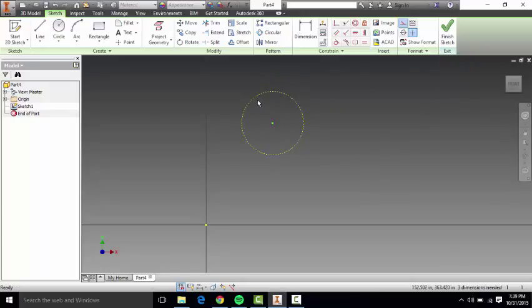And we can see that it is yellow and dotted, unlike if we deselect this and click on the circle tool again. A regular circle is green and solid. So construction lines won't be printed by the laser cutter, so you can use this to your advantage to help you make more complex geometry without worrying about the laser cutter cutting on these lines.